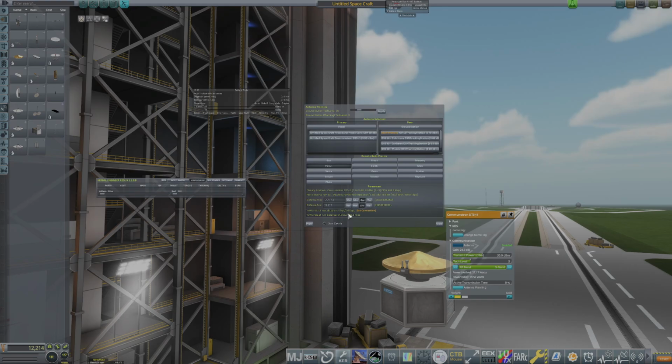And now we can see that at maximum distance, there's no connection. Why is there no connection? We can still receive data from Earth, but we can't transmit data from Earth. At the minimum range, we can. So we can roll the dice and probably do mission planning properly and say, what is the maximum distance I will be away in Venus in my mission time frame? Or if you want to play it safe, you can just increase the transmitting power of your antenna.